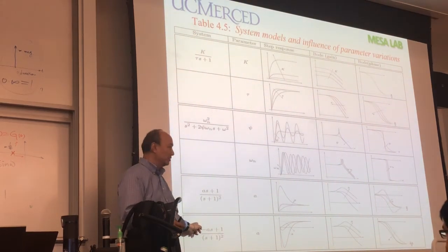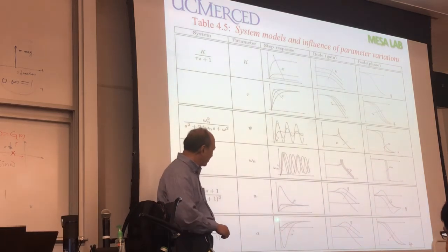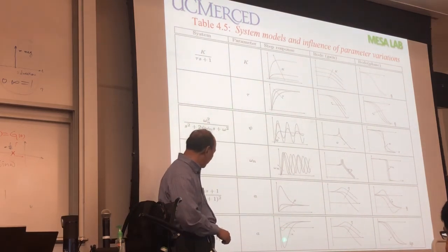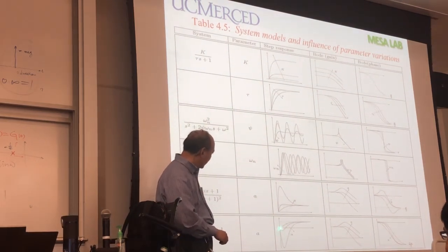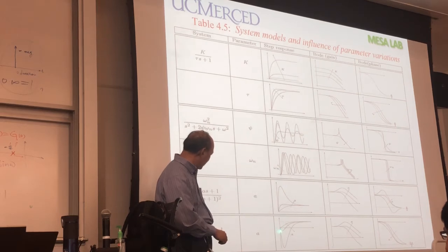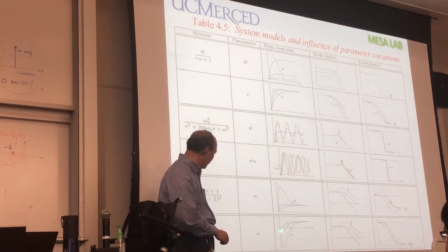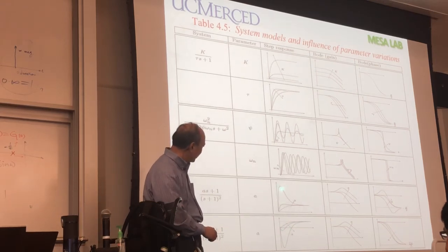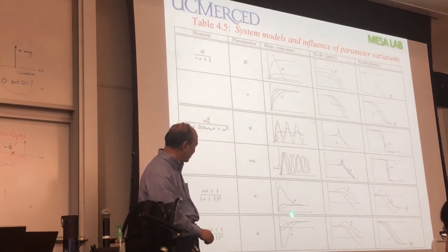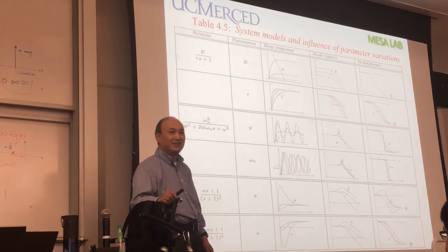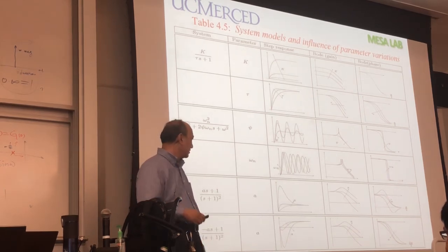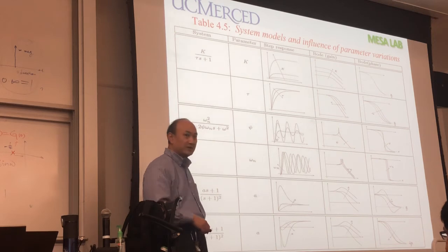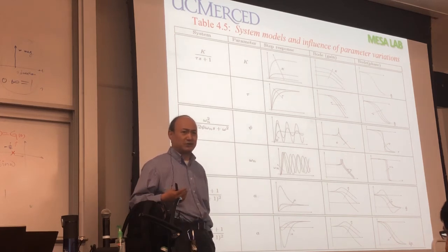zero. So you can see that for a step input, as A goes up, initially with A small, it should be like this, with A big and A big. So this is undershoot, this is overshoot. Okay? You see it? This is pretty weird in practice because it's counter-intuitive usually.